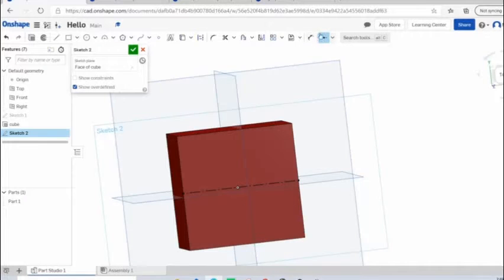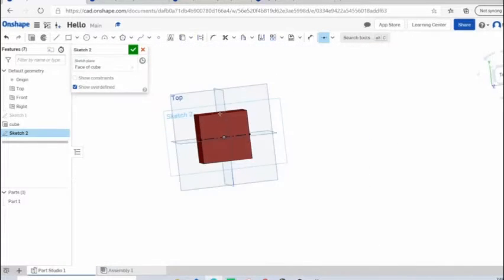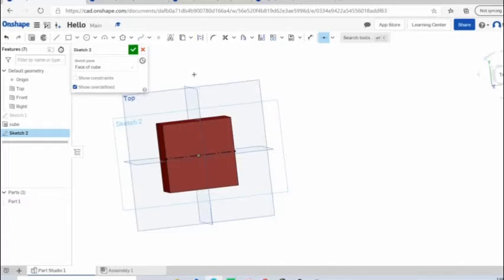And you might not think of using this stuff as super important to define your document, but it really is, especially if you go further in CAD, because it can really make or break. You'll get all sorts of red images over here and red text, and it will be a fever dream if you do not make sure to define things. And dimensions are a fine way to do that, but they're not as precise, and you really don't want to define things to the outer edges of stuff. And the more we can use midpoints and coincidences, the better it is.